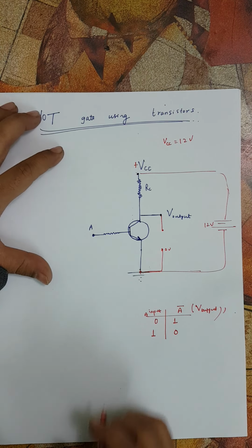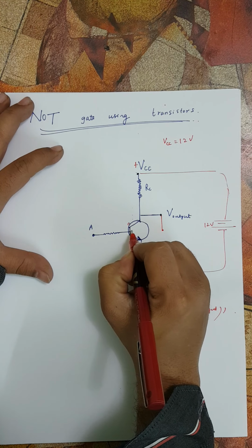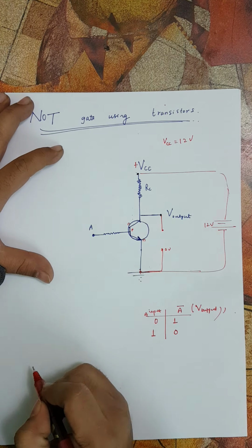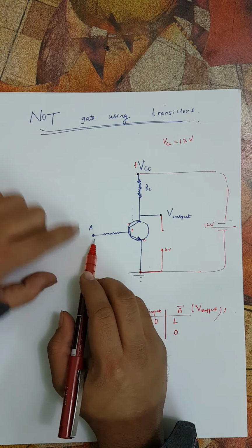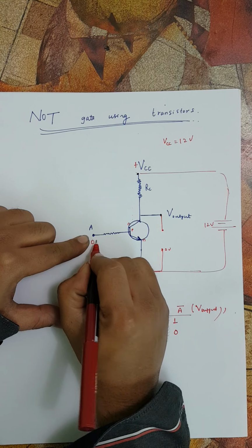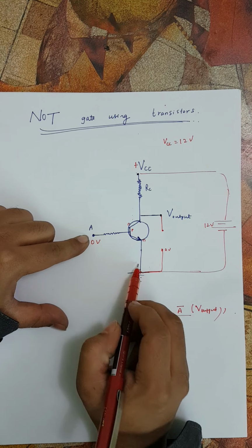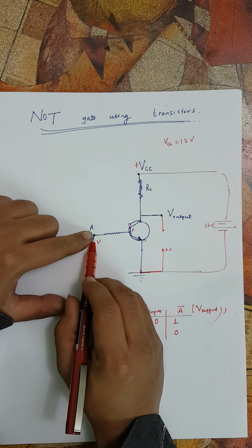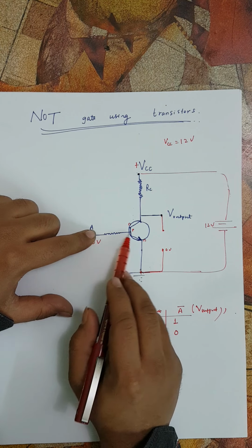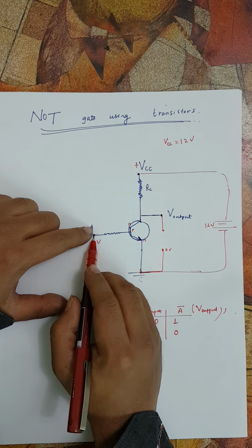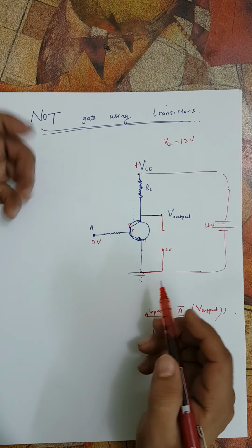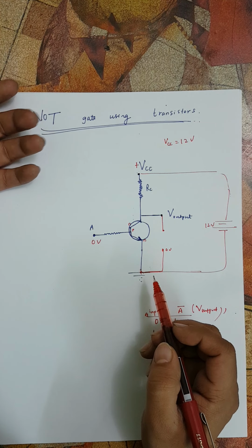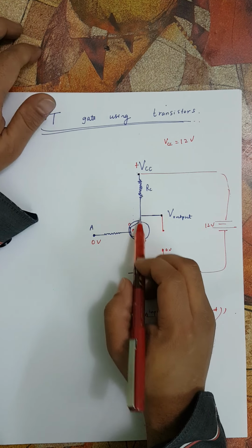So as we know, this is an NPN transistor. When we don't bias it, that means when we supply 0 volt here, since there is no biasing on the base-emitter side, nothing happens. Which means when we don't supply any voltage across the base and emitter p-n junction, no input voltage means no input current, and no input current means no collector current, so this current becomes 0.